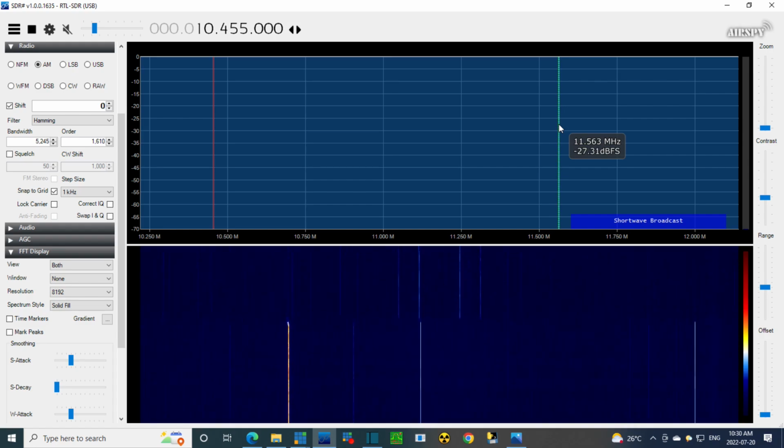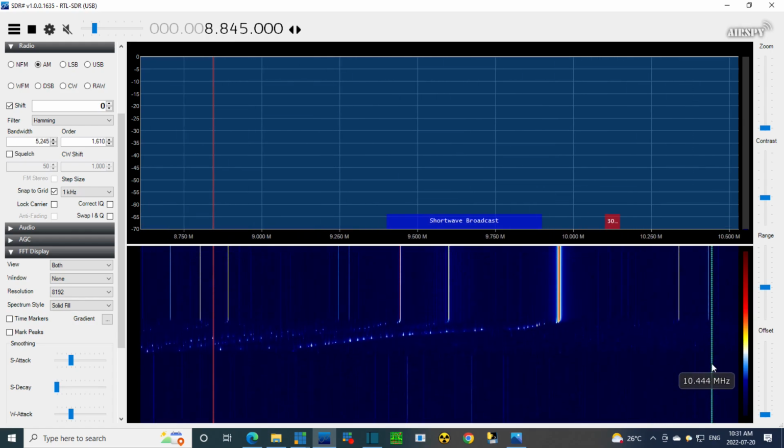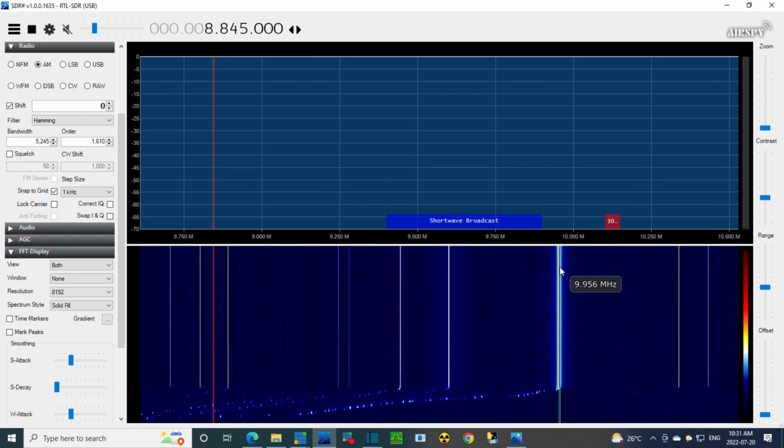So the local oscillator hasn't changed very much. Let me tune the radio to 9.5. Now we've got to add 455, so just go just below it a little bit. That should put the local oscillator at 10 megahertz. It's just off the scale. I'm going to move my scale over. Do we see anything pretty strong? Look at that. Big strong thing here right near 10.